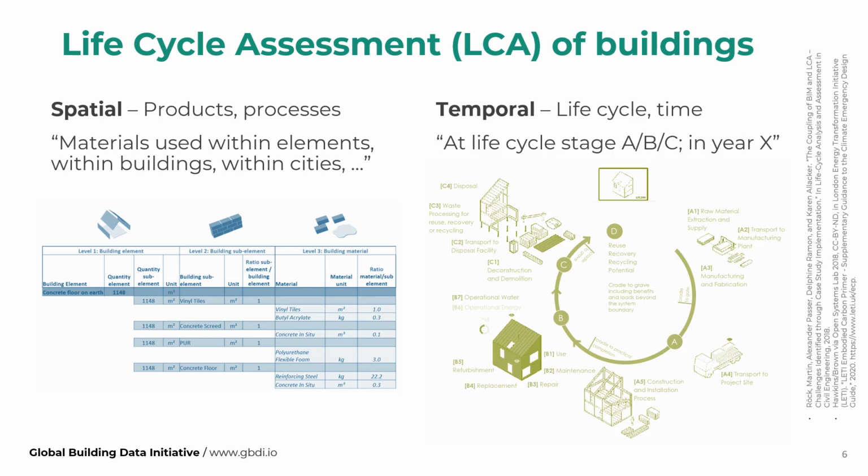Then we have the temporal dimension, where we are trying to really capture the whole life cycle of buildings. This means different life cycle stages in our international norms. We usually have the nomenclature where A is the production stage and the construction installation process. B is the use phase, where, as I said before, we have building operations, so the operational energy, but we also have the embodied emissions of replacement, refurbishment, and so on. And then the C stage is the end of life with all the processing that goes on for deconstruction and eventual end of life treatment.